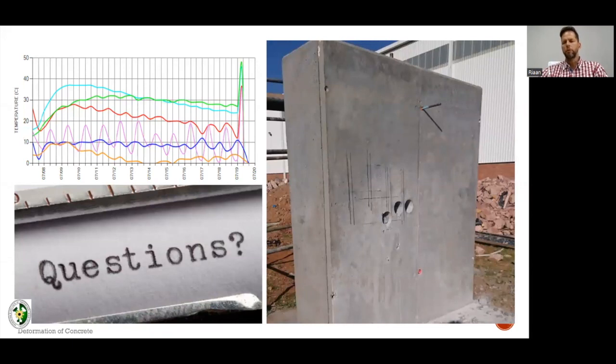So how you would establish whether it's efflorescence or ASR is if you drill into your concrete and remove the core drill, and you find that your aggregate particles in the core have a white rim around them, even inside the concrete, you know that it's ASR. If there's no white rim, then you merely have efflorescence. Now, efflorescence wouldn't necessarily have that many cracks, really. So that could also be an option to look at.